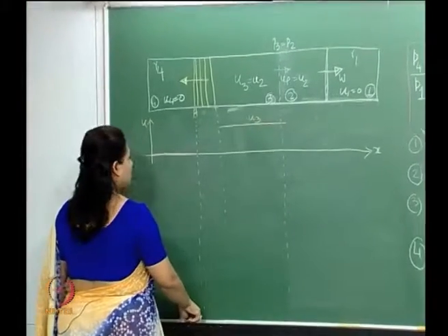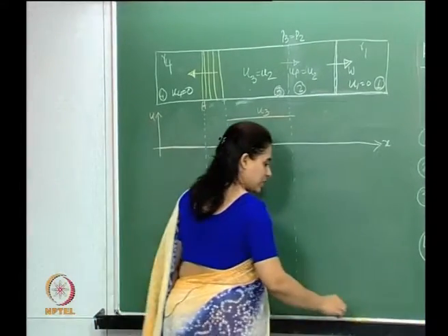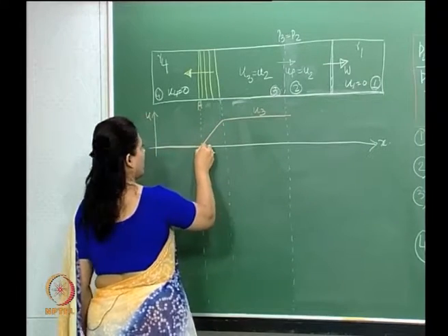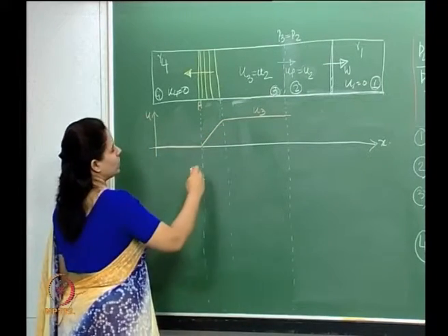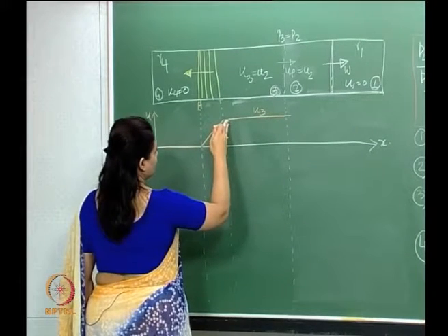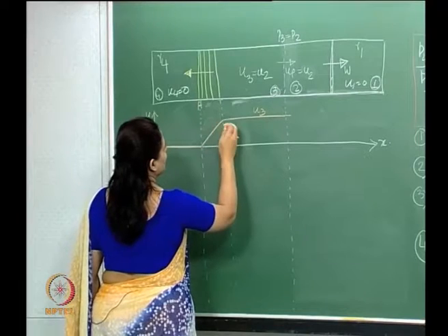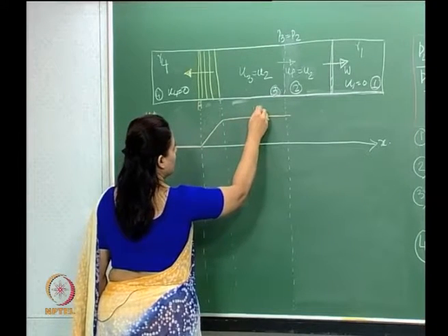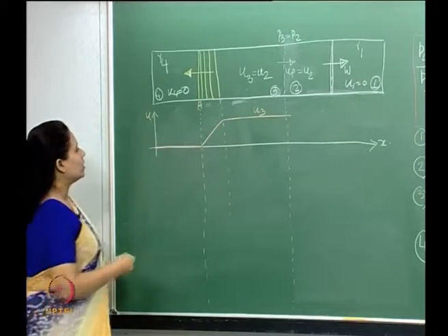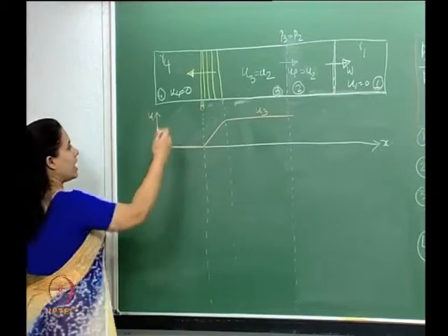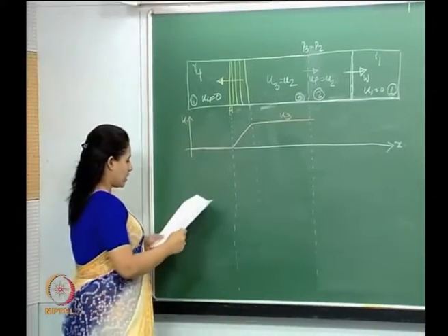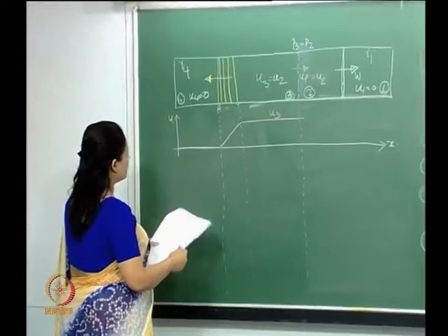So, within this region, what we are basically saying is that we have a velocity which is u3, and then that linearly decreases to 0, right, as the expansion fan moves into the quiescent region. Okay, so that is the velocity.